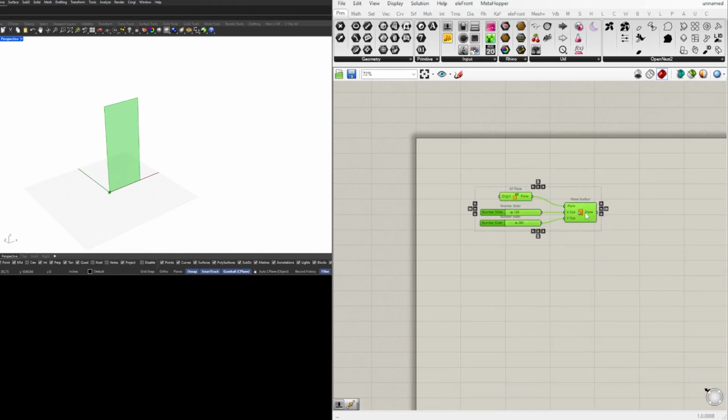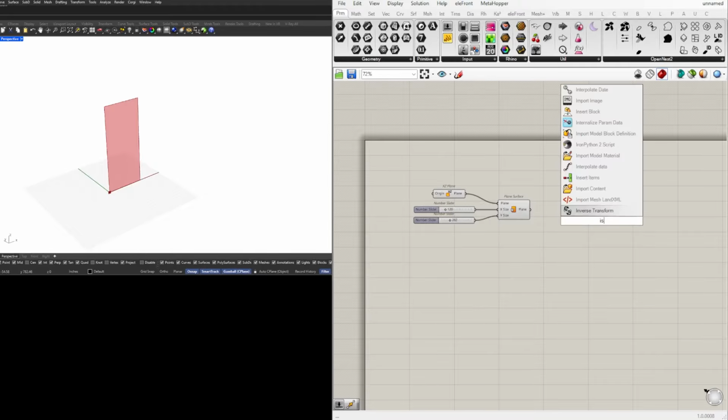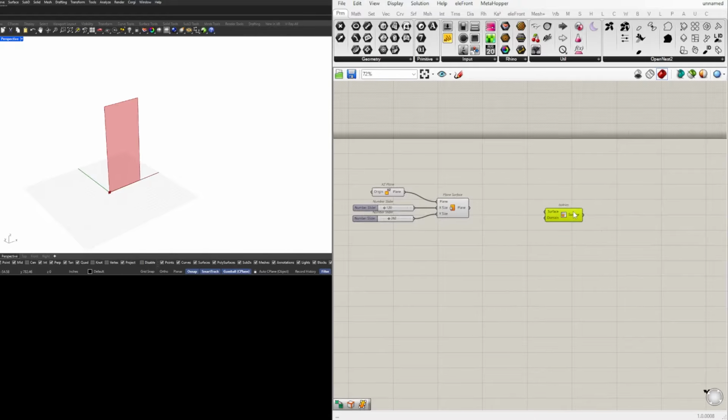Now in Grasshopper, when you have a plane, you have the ability to subdivide it. Now by using the default components that come in with Grasshopper without having to download any other plugins or additional things, the most simple way that you can do a subdivision is called isotrim. Isotrim is useful because you can plug in this plane into the surface, and the domain is how you want to subdivide it.